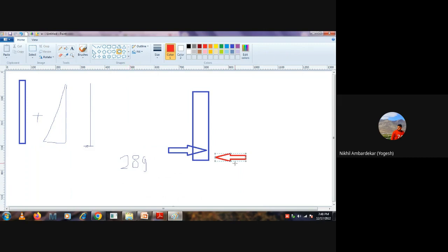So what is the governing? Obviously my this value is more, so I don't need to consider this one. Shear force is always considered maximum. But for reinforcement, even though you have maximum for soil and some less for water, you have to consider both bending moments, because you can optimize the inside and outside rebars based on that. Got my point? Yes, sir.